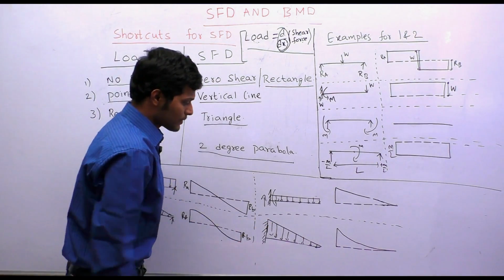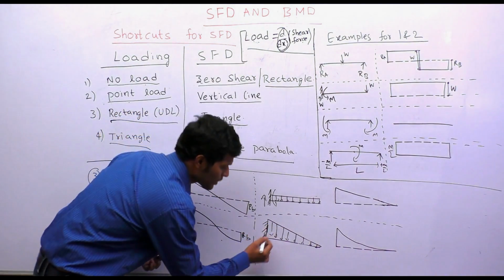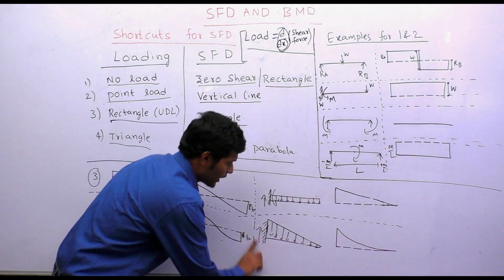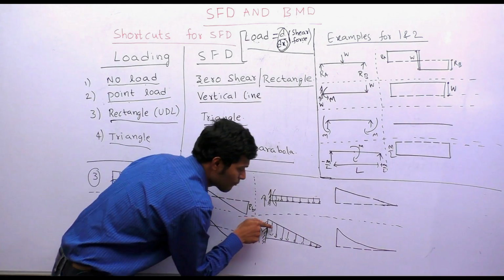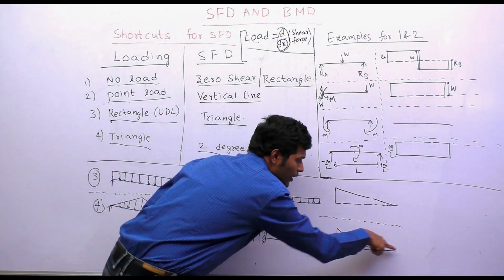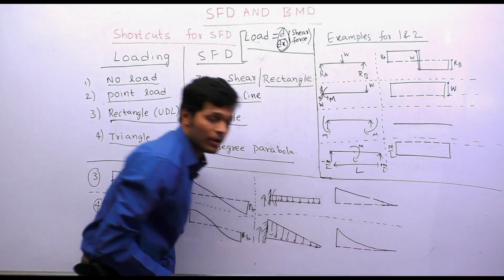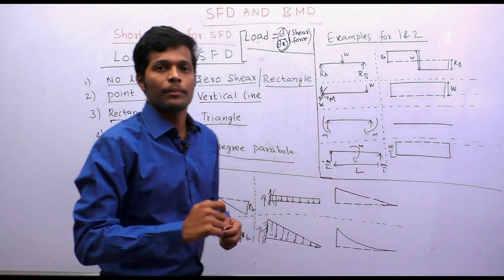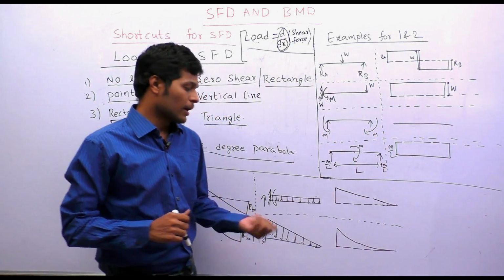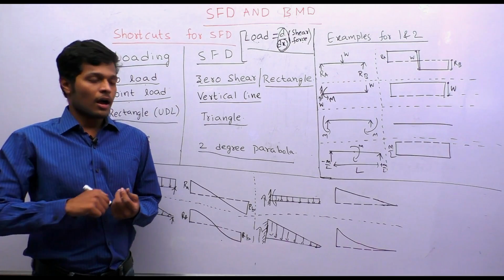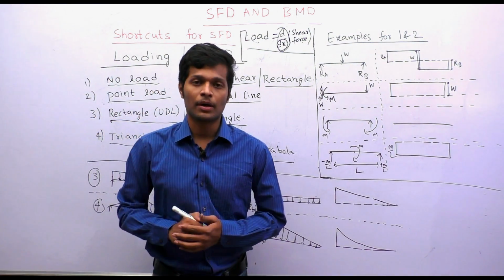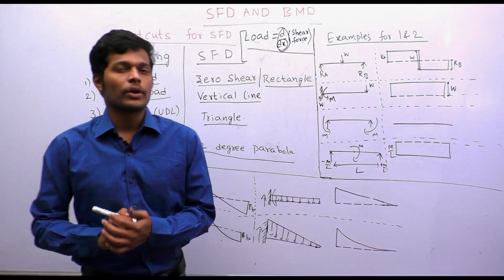Same here also we can see. So when there is a loading diagram, obviously we get a reaction here. So we get a reaction and it is a falling parabola because the load is downward. So I have drawn a falling parabola like this. Okay. Now in the exam, suppose sometimes they give convex parabola and concave parabola, how to identify whether the answer is convex parabola or concave parabola without solving, how to identify this.